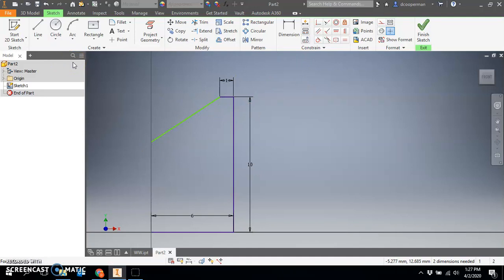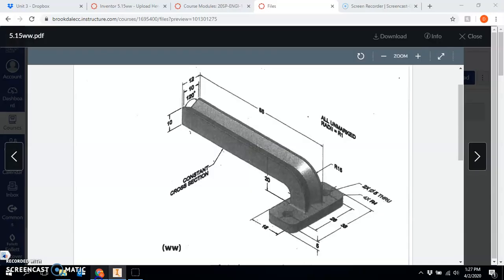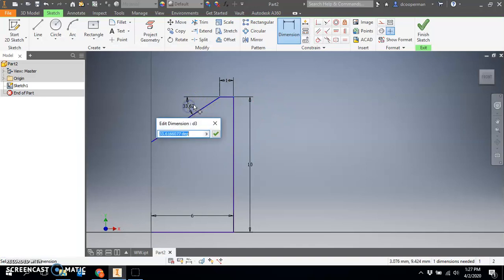Now I'm going to go ahead and add a dimension for here. And I'm going to say a dimension between these two. So bringing back your geometry days, if the angle from here to here is 120, what will be that little angle over there? Well, if we cut it halfway, then that angle right here would be 60, and that would be a right angle right there, which is 90, so we have 30 left. So that little angle right here will be 30.